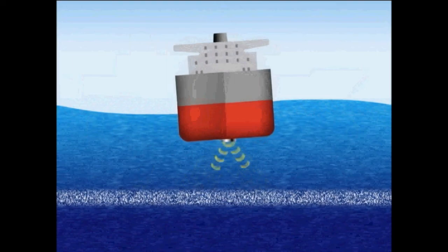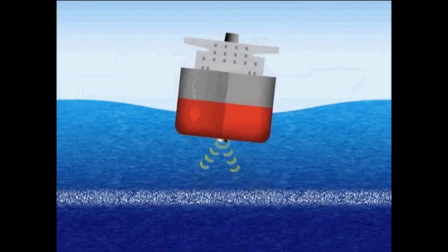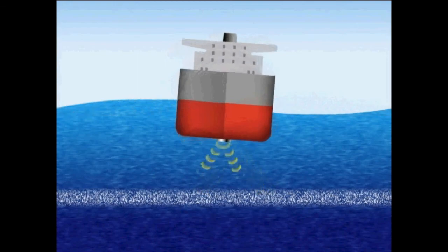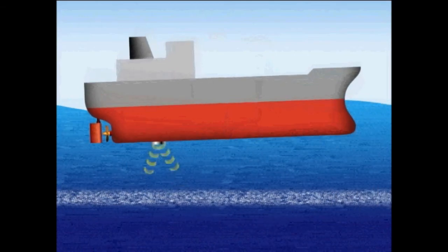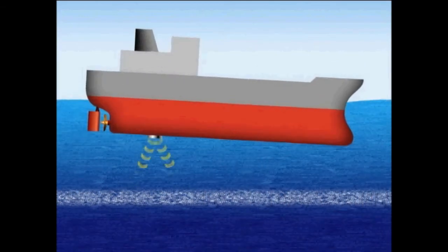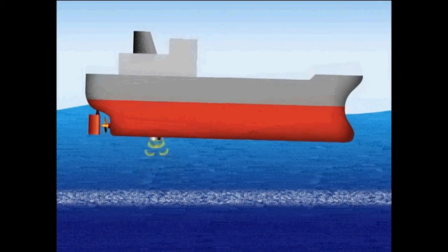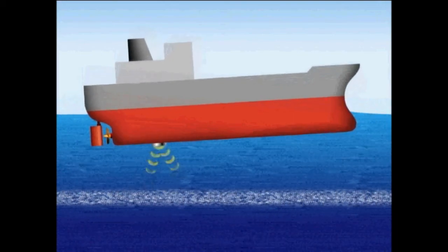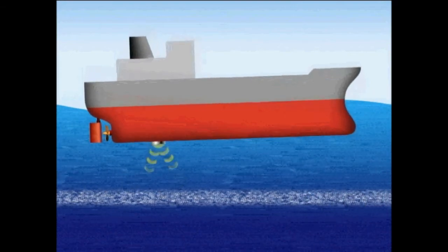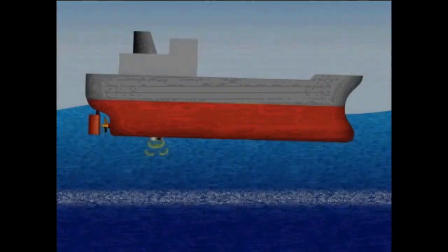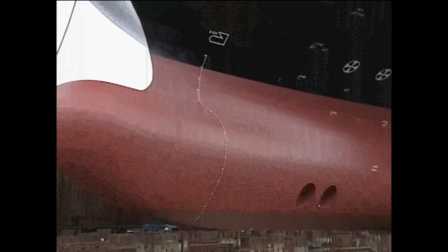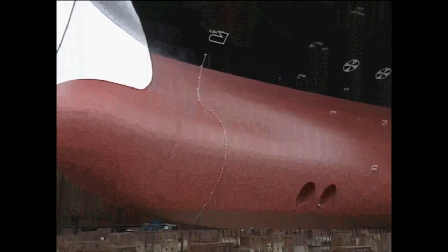This method has made it possible to significantly reduce the error margin due to hull vibration from rolling and pitching, and the error margin of the speed measurement due to trim changes. Highly accurate speed measurement in rough seas has been achieved. Recently, it's become possible to make the transducer small enough to fit in the bow, where it's less susceptible to the effects of bubbles in the seawater.